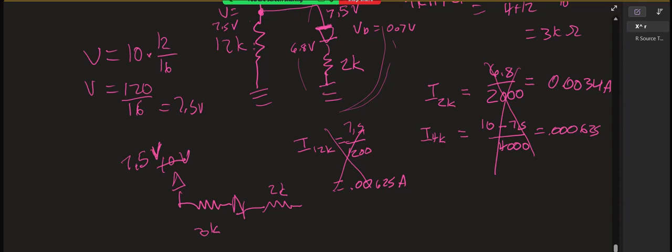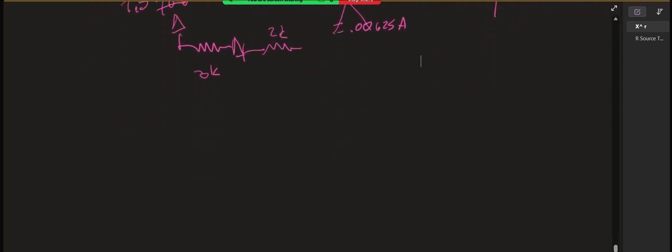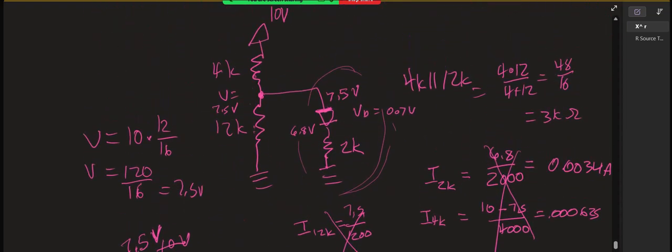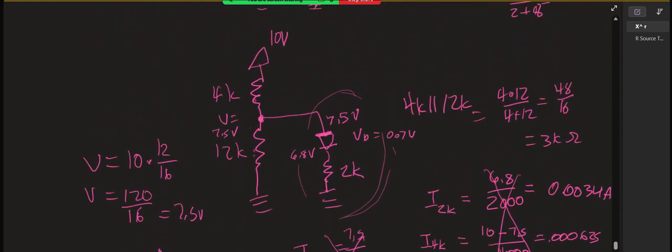You mean change this 3K to a 5K? And then get rid of the 2K, because those grounds would be connected in the same way, and they would just be in series with the other part of the Thevenin resistance. I think so. I just hadn't thought that part through. So hold on. Yes, I can do that. I just hadn't gotten there yet. Okay, so let me go. I heard confusion, and I don't blame you for being confused. So let me go back and just tell you what, because I messed you up.